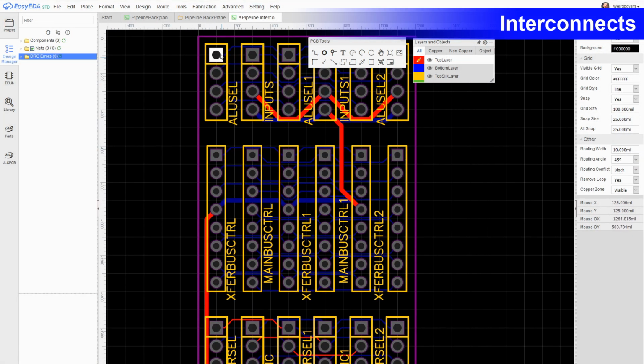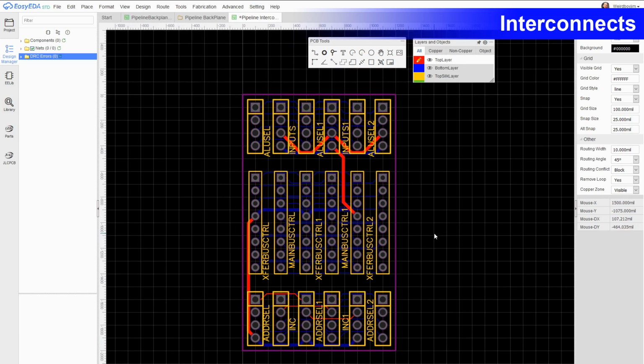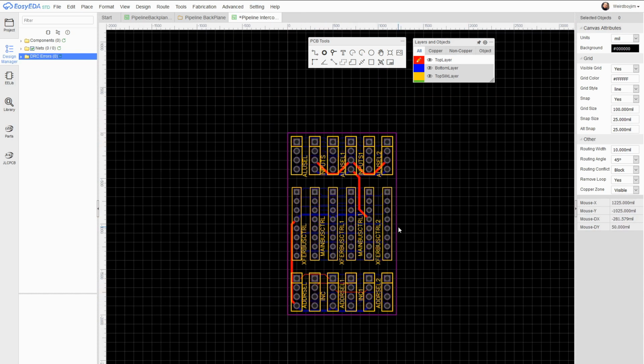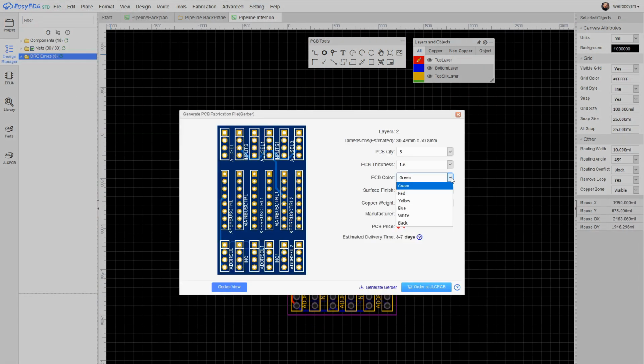So if I solder pins into the left and the right hand side ones and then just drop this little PCB in between the 2 back planes, it will make all of those connections. And then for inputs here and any of the others I end up wanting to connect to otherwise, I can just wire some additional pins in the top here. So it's going to cost me $2 to save me a whole bunch of wiring. Totally worth it.